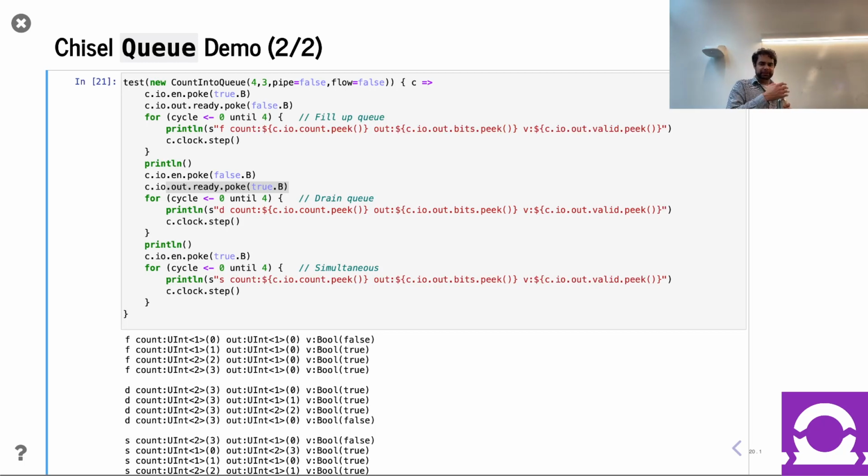But as a good aside, I'll mention this for others on the recordings, people forget. Chisel, by default, even though there was that don't care annotation a few slides ago, for the most part is a two-state language, meaning values are either 0 or 1 per bit. There's no X's or Z's really in the language. In simulation, you have things that are uninitialized.